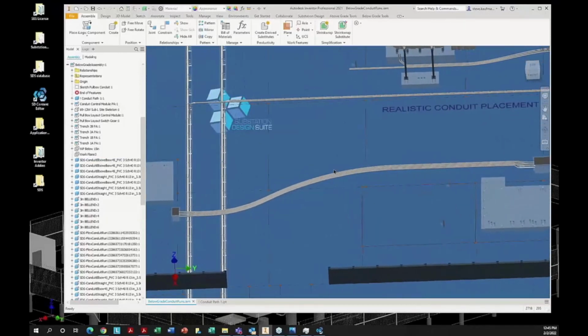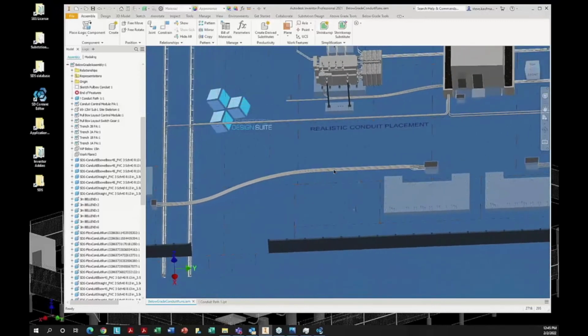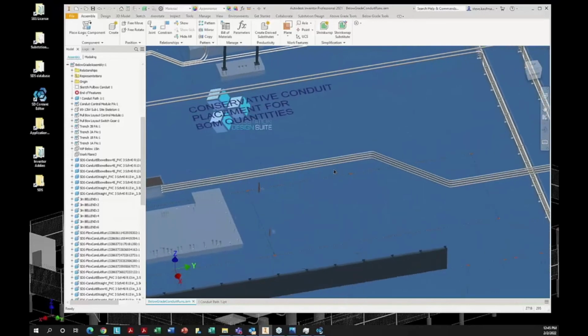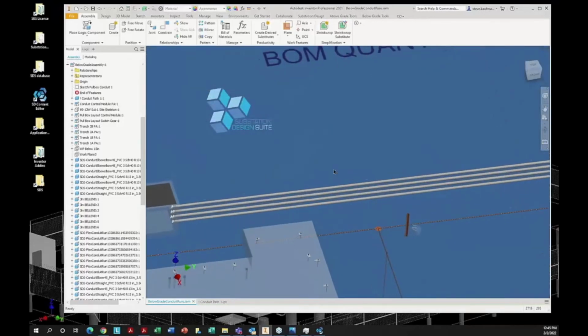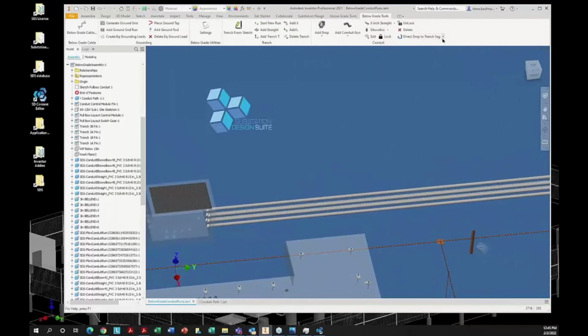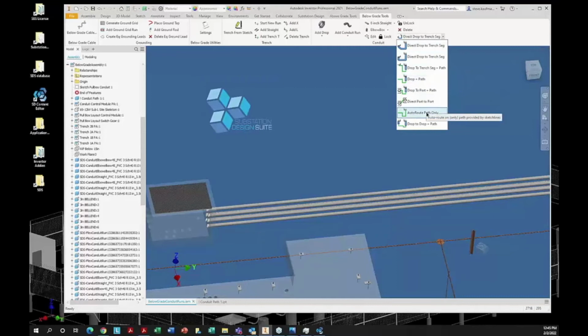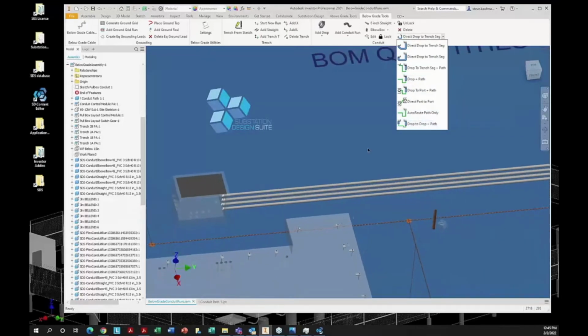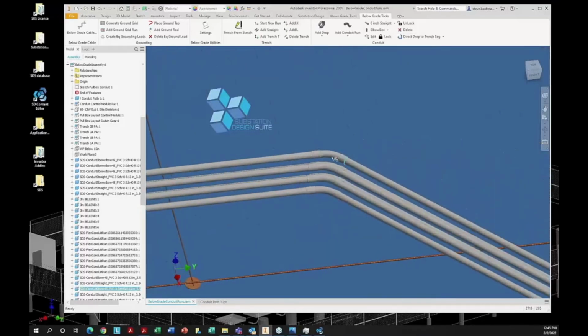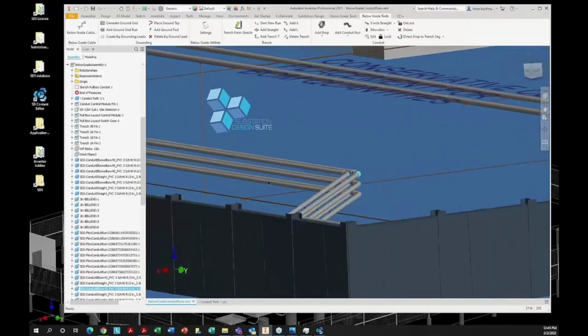So in talking with others, like Josh, he mentioned, well, they may want to do it this way. So in this way, I use the traditional type of conduit that we have using the below grade tools and the drop plus path, or my auto route path only, where I create a path and I follow that path. And here you can see I just follow that path. So when I do that, it places parts in it. So now it's picking elbows. You can see it's stacked.